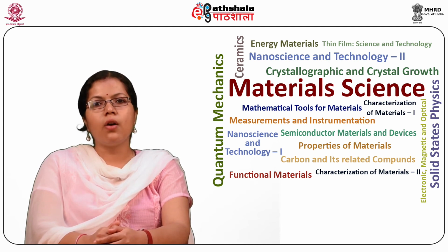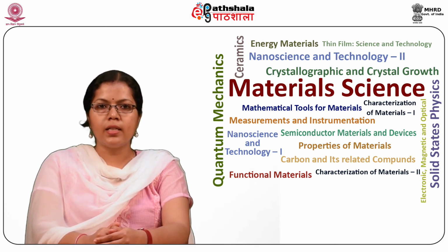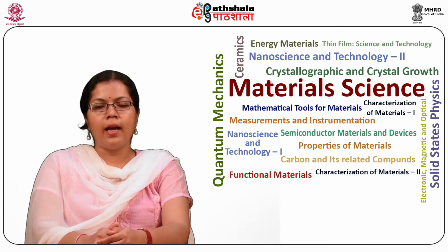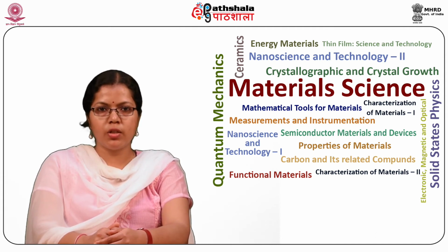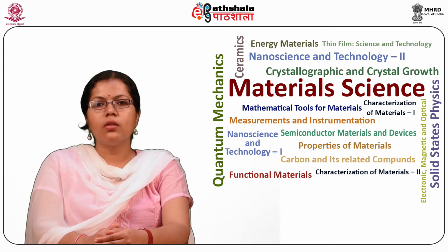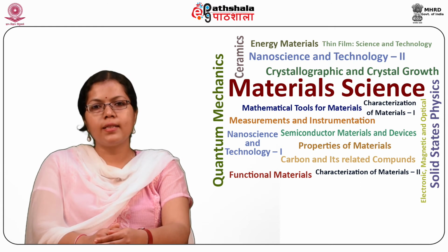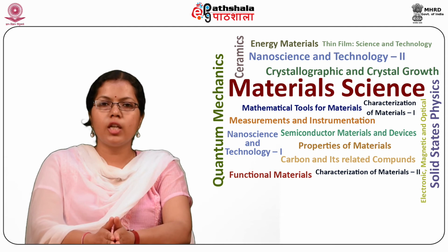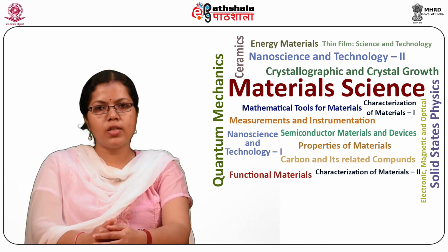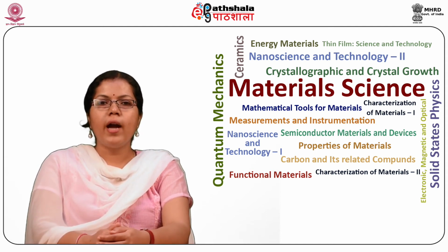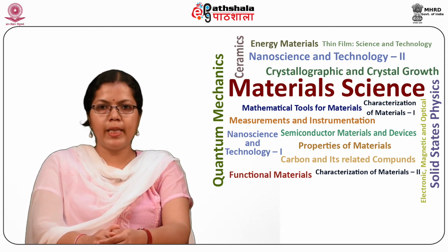The sensitivity of the device is given in terms of cell current at a fixed voltage and a given level of illumination. The major drawback of the photoconductive cell is that it is quite sensitive to temperature variation and therefore unsuitable for analog applications. They have wide use in industrial and laboratory control applications.